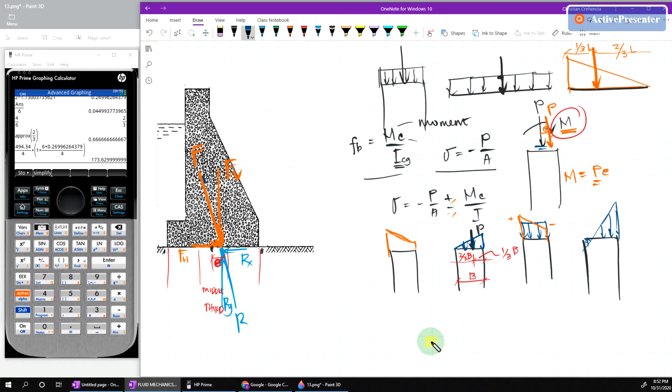Pero sa footing or sa foundation or sa dam, okay, sa pagdating sa dam, hindi natin kino-consider yung tension doon sa soil pressure natin. Kasi nga nakapatong lang naman tayo dun sa soil. Okay? So, kaya importante na malaman natin kung saan located yung ating resultant force. Okay.